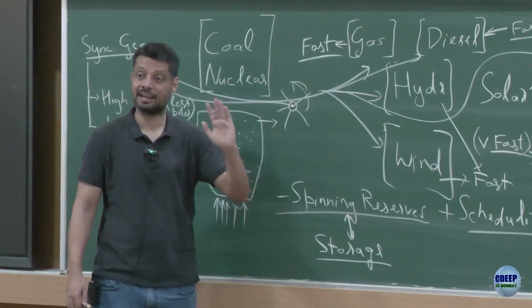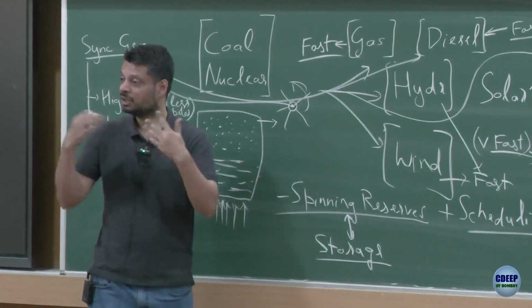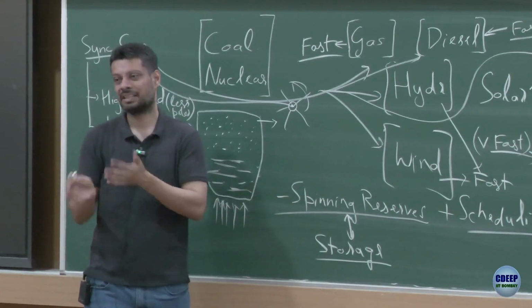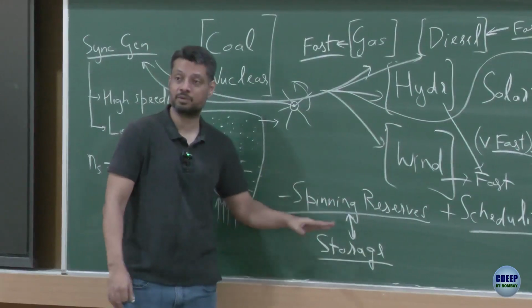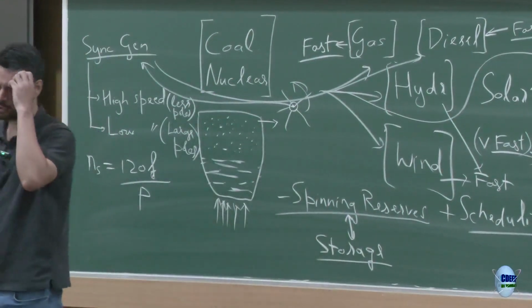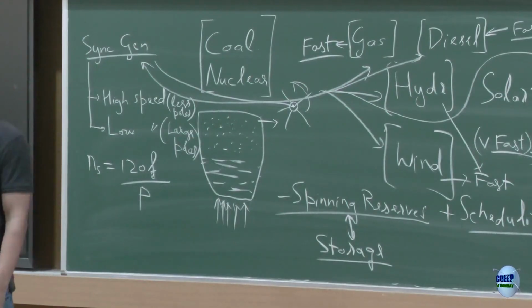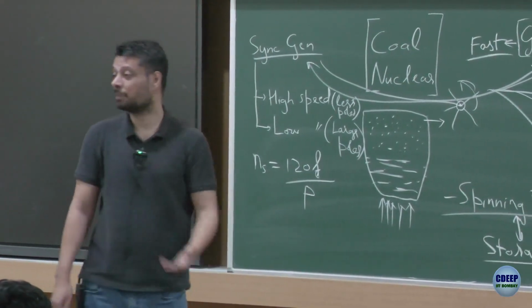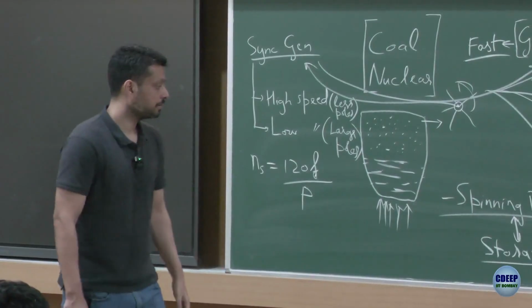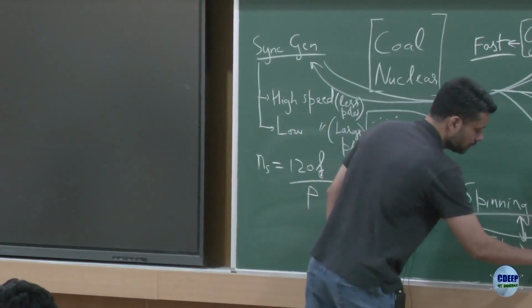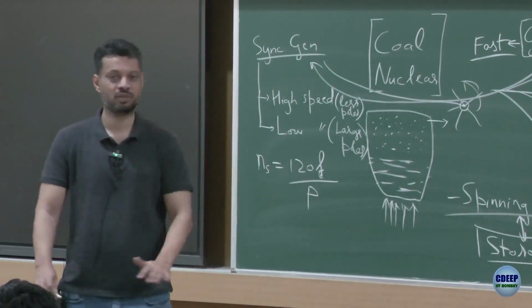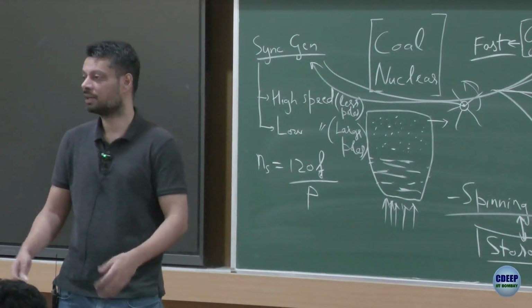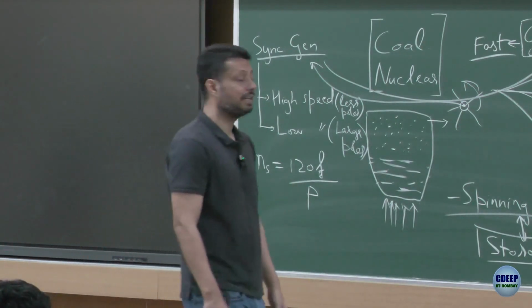That means have a coal plant running, multiple coal plants running without even producing power. So they are still polluting, it doesn't really add up. So people are now talking about using storage, which is like a substitute for spinning reserve to some extent. Storage could be batteries, storage could be hydro. There is compressed gas storage as well. These are different types of storage technologies people are talking about, which are slowly getting integrated into the grid. As of now, we don't have much storage in the grid, but as we move forward, we expect a lot more storage to be integrated.